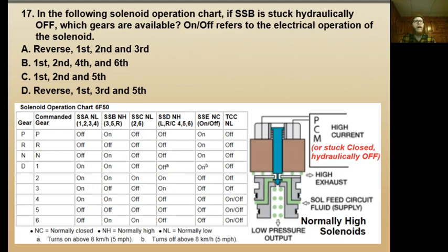If we're matting the accelerator, we want that shift solenoid to come on, and to come on with some serious meaning, so closer to 100%. If grandma's headed to the grocery store, then the shift solenoid may only open up 30% because she's putzing along without much torque coming out of the engine, so we can have a slower shift, which is what would occur with a solenoid that's not allowing as much hydraulic fluid and pressure through it.